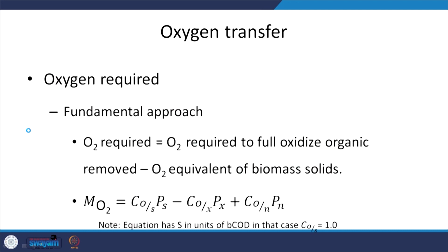And the next aspect, as we discussed briefly, was oxygen transfer. Until now, we looked at the concentration of microbes that we need to maintain, how much time the microbes have to spend in the system, which is the solid retention time, right, and the design variable, which is the concentration of our waste, or the food to the microbes, the substrate leaving the system. We looked at these aspects in different contexts.